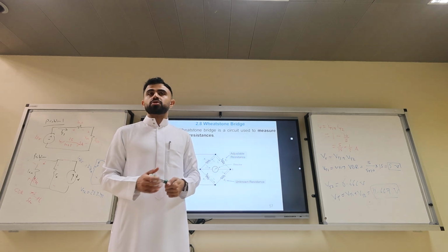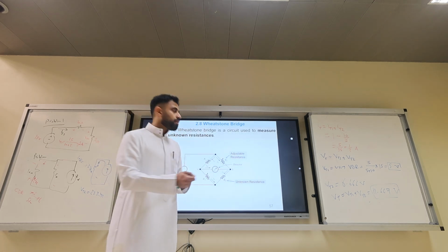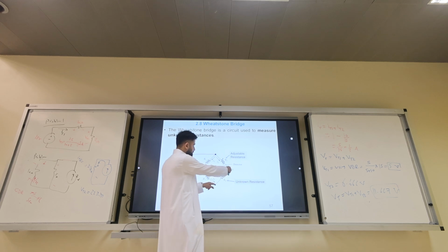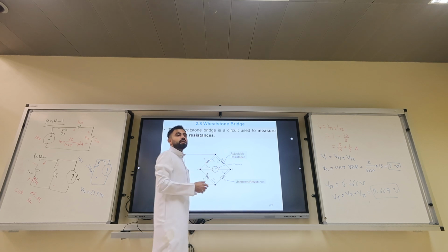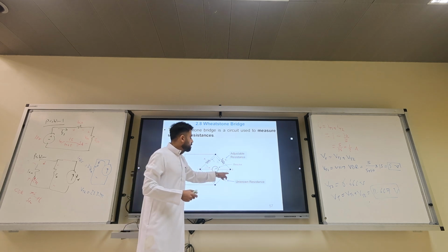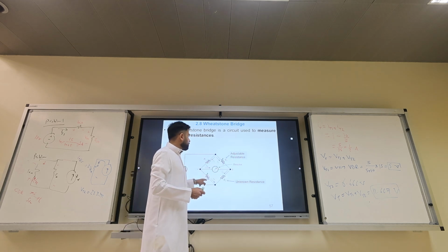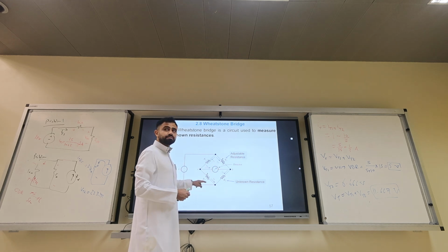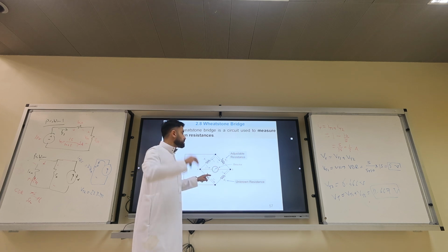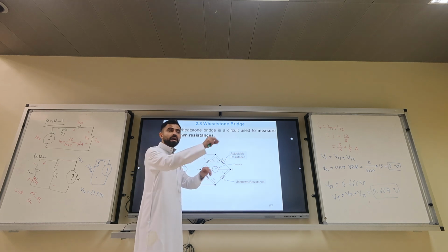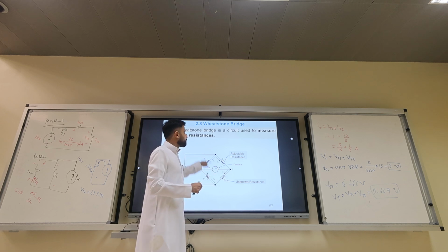Ohm meter. The ohm meter in the lab works like this: it has two terminals, you put your unknown resistance across them, and it does these things inside and calculates the current, and based on the calculations, you know the unknown resistance. It has adjustable resistances R2 and R3. For the digital ohm meter, those are calculated numerically, but in the 50s or 40s, people had to do it manually to measure the resistance.